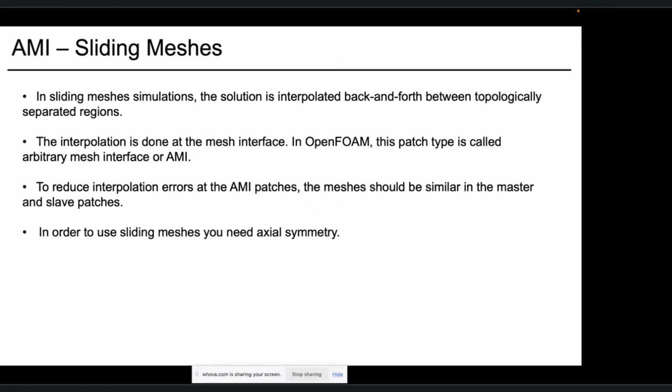And the fourth kind of dynamic mesh motion is the arbitrary mesh interface method, where it actually involves different sliding meshes. And the example that I previously showed you using this is the flapping airfoil motion, where we have a separate rotating part and the outside stator part. And within the rotating part, it undergoes a sliding motion at the interface of both these mesh components and achieves the motion of the body.